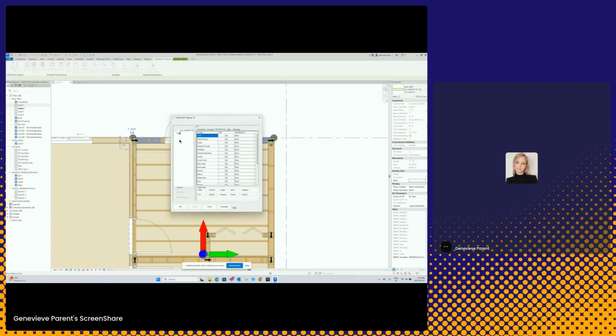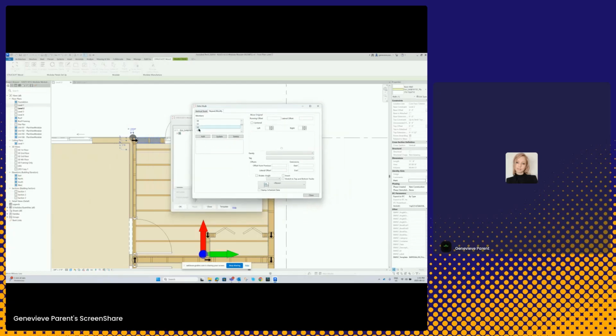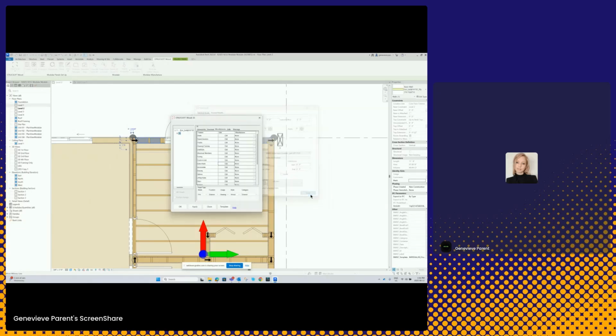How about we add, oh no, we have joins here. I might not want to start adding extra studs at the end, but perhaps we could add extra studs. We will do a repeat modify and we'll just select one of our S verticals. Now we'll select S4 and we will make a slight change. Perhaps we want to turn this into a 2x4. I'm just going to hit add and I'm going to hit close. I want to keep this simple and I'm going to hit apply.